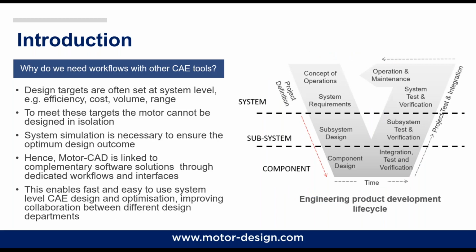So now that we have introduced MotoCAD, we are going to answer the question, why do we need workflows with other tools? The design targets are often specified at a system level, as for example, the efficiency, cost, volume, and range. And to meet these requirements, the motor cannot be designed in isolation, but has to account for a wider system level simulation, since it allows us to ensure the optimum design outcome.